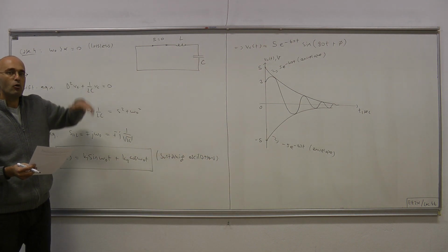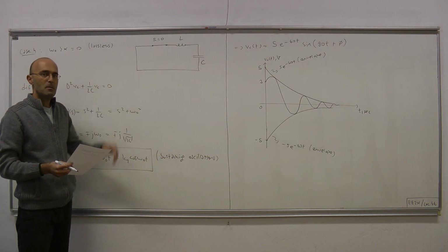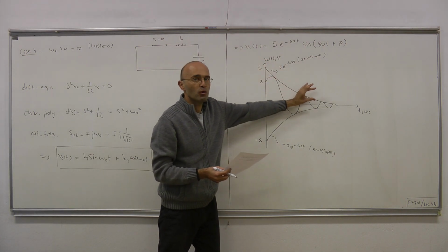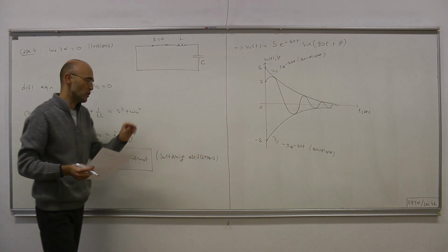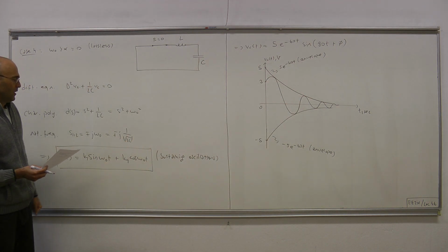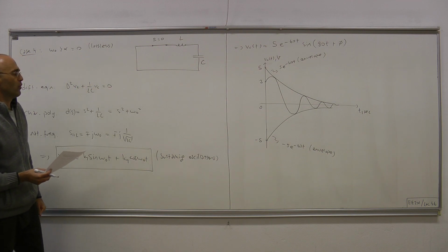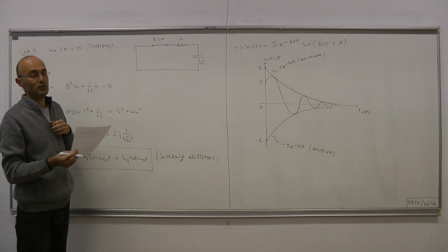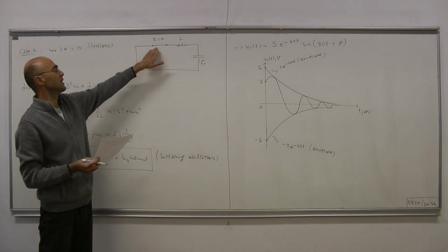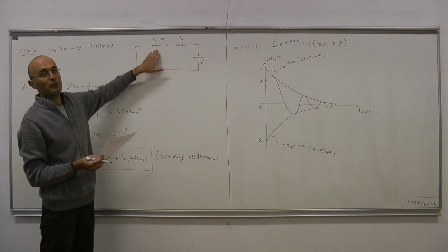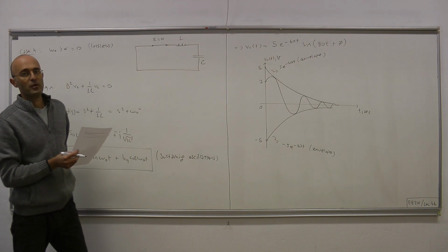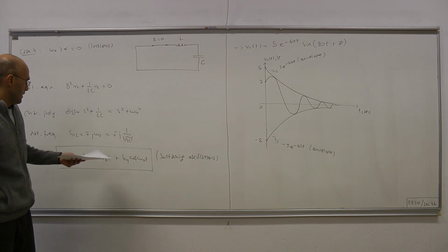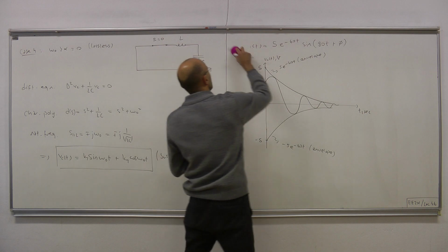That is, the oscillations will always keep going with the same magnitude, whereas in the previous case the magnitude becomes smaller and smaller as time goes on, decaying to 0. In this case, the oscillations continue forever at the frequency omega 0 with constant magnitude, or amplitude, because the energy has nowhere to leak out of the circuit. We're considering the ideal case where we have no resistance. Let's apply this to a numerical example.